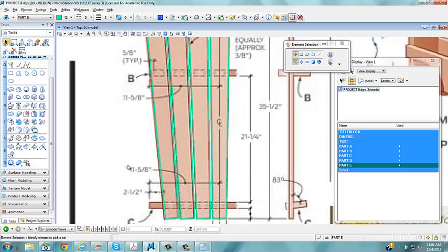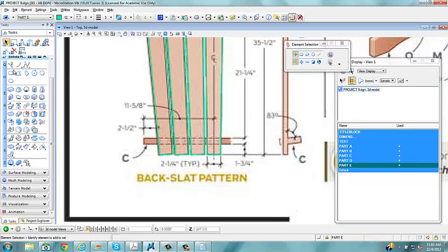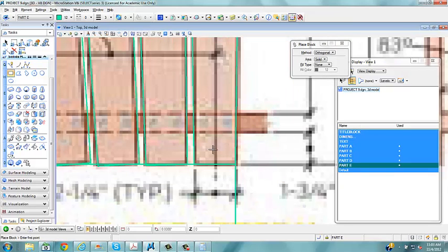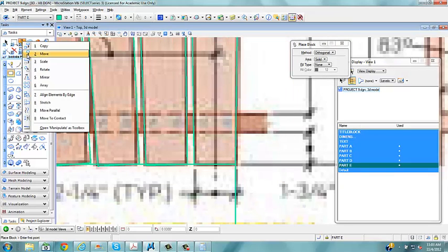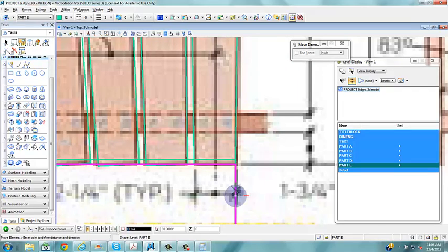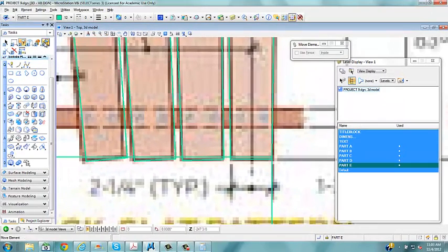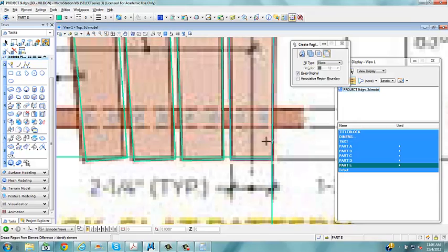and actually before I mirror them to the bottom, let's square this up on the bottom edge. So I'm just going to draw a block down here, and I'm going to raise that up about 1/4 of an inch. 0.25. That's too much. Maybe 1/8 of an inch. 0.125. So I'm getting the bottoms of all of these. So when they actually curve, it'll give me a nice clean end. It'll do the same thing. Boolean difference.